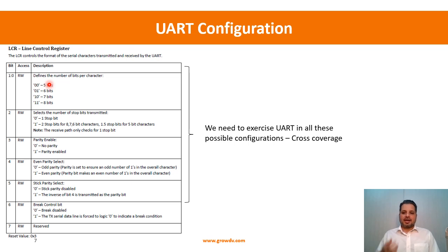I can take a simple 6-bit vector and keep incrementing it so that I go through all the combinations. I can randomize it, but since I know I must hit all of these, I can as well take one 6-bit vector, keep incrementing it, go through all the possible combinations, and program it into LCR. Note that only programming is not sufficient.